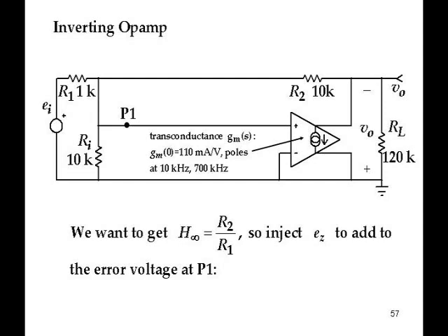There's a resistance Ri there that isn't really essential in the basic model, but you'll see the reason that I've put it in a while. At the outset, you can tell that the Ri doesn't influence the result very much because it's connected across the front end of the op-amp, and that's almost a virtual ground to the extent that the loop gain is very large. So there's very little signal in Ri, and it makes hardly any difference to the final answer.